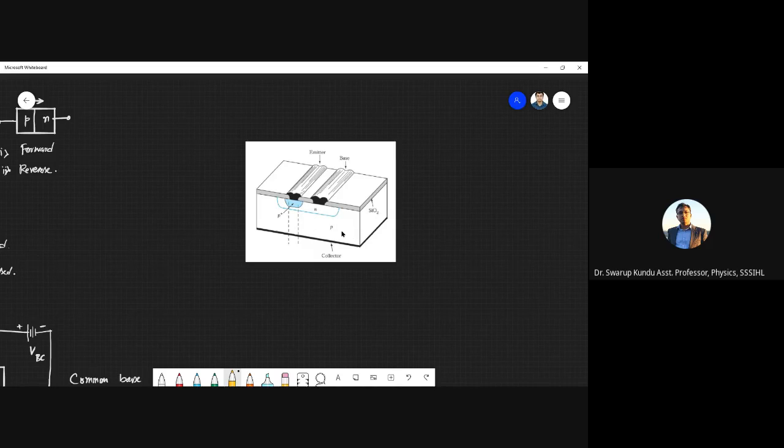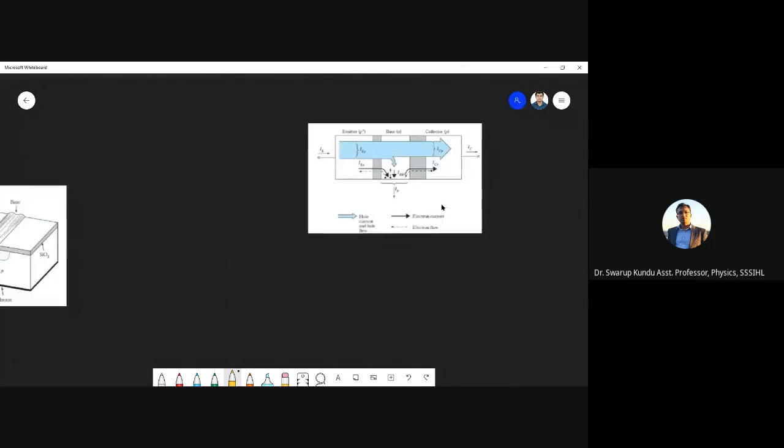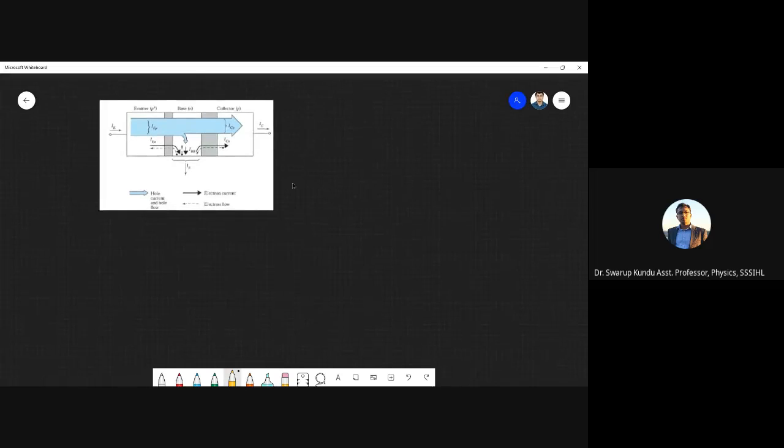So first, you start with just a P-type material, and then you make N-type, you make P+ type material by injecting ions or the dopant ions, and by doing selective masking. It's the same as the PN junction diode, but here a bit more complicated. Okay, so now let's go back to the current equation of a PN junction.